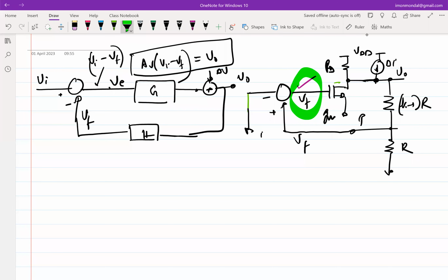So the input of the error amplifier goes to 0 if the amplifier gain is close to infinity, right? If the amplifier gain tends to increase, the input of the amplifier will tend to decrease. Okay, and that is the only fixed property of a negative feedback loop. So you can analyze how the loop works by simply figuring out what the input of the error amplifier is, setting it to 0, and then going about analyzing the loop.